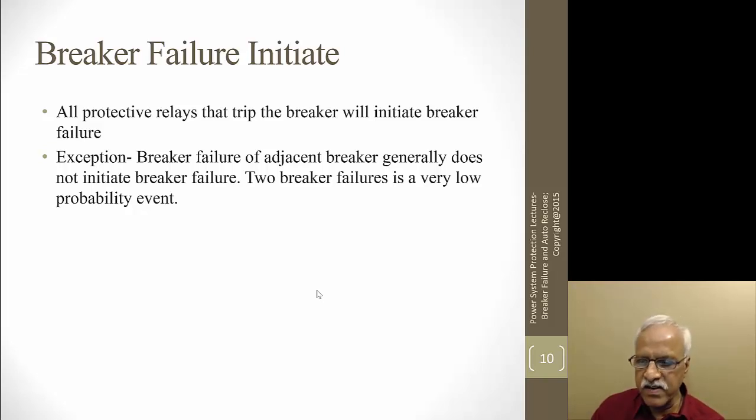So this is a brief introduction to most of the breaker failure schemes. It is a very simple method. You have to make sure that the overcurrent element is set sensitive. You use auxiliary contacts for that, and then there is enough margin to cover the total reset time, including the operating time and the reset time of the overcurrent elements that are used in the relay.